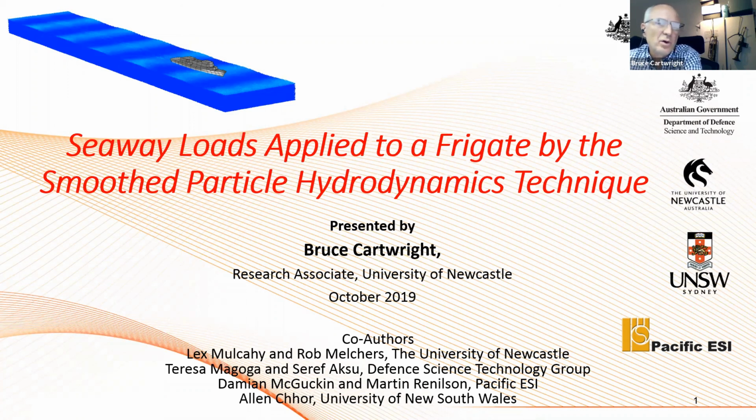Obviously, the whole crux of this is to be able to predict the stresses in areas of stress concentration. Whether or not we'd be influencing at the design outset, that wasn't really the aim for the tool, but we're more looking at existing structures and stress raisers that have resulted as a consequence from use. So either fatigue cracks or damage, if there was an accident or an explosion or something like that, or loss of material due to corrosion. So that would be a little bit different to the approach, and probably the results, that you want from a design outset. But ultimately, the principle is the same.